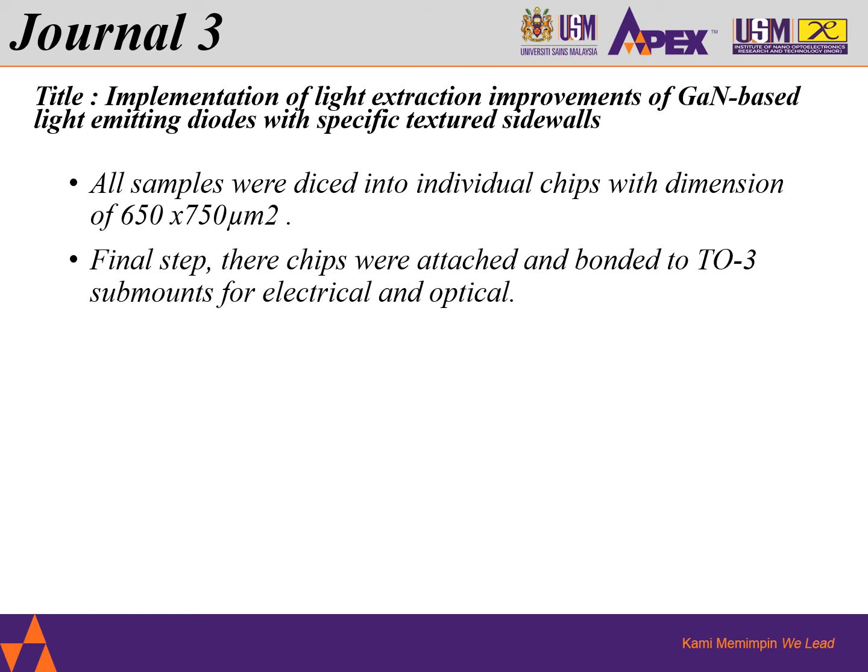All the samples will be designed as individual chips with the dimension of 600 micrometer times 750 micrometer square. In the final step, the chips will be attached onto the board sub-mount for the electrical and also optical characteristics.